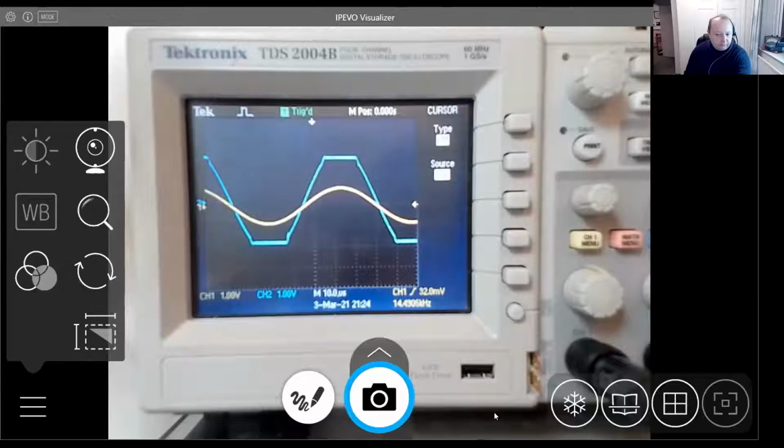So, this phenomenon is called clipping. The operational voltage of our device is running on plus and minus 3.3 volts, and we've got a gain of about 2.5-ish. So if the input voltage rises above 1.5 volts, you can't have more output volts than what the power supply is generating. So we get a little bit of clipping.